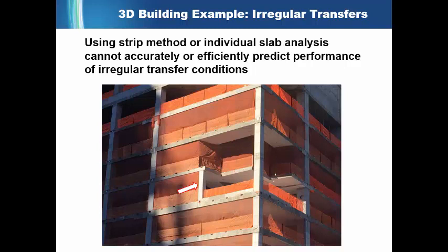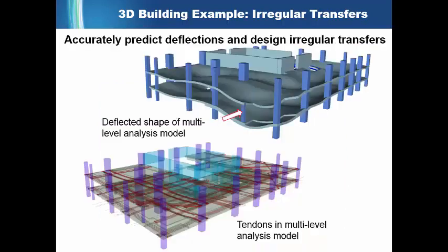ADAPT Builder is able to easily handle complex and irregular conditions in your projects, unlike other programs which would have to do this piecemeal. The deformation compatibility in a situation like this is easily captured by the Builder software. As you can see here, we can extract these two levels and view how, as the column deforms downward, the slabs move with it.